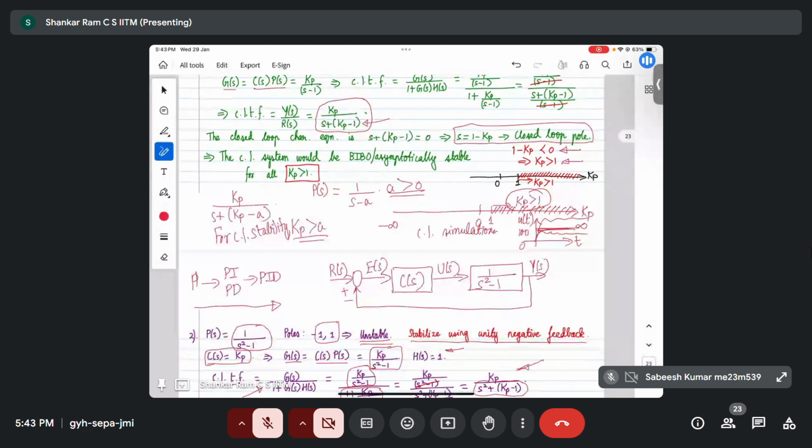So my answer to your query would be that rather than the order of the system, I would be looking at the distribution of the open loop poles. In other words, how many open loop poles do I have in the left of plane? How many in the right of plane?